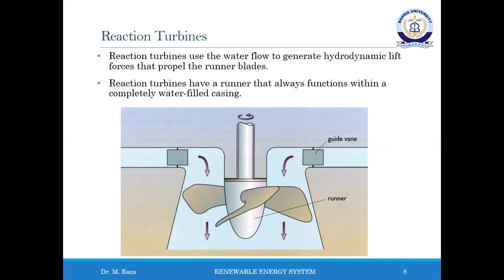The propeller turbine, as shown in this diagram, is an axial flow turbine with a propeller-like runner and 3 to 6 runner blades depending on the design head. The runner operates like a reverse boat propeller. Various configurations of propeller turbines exist.